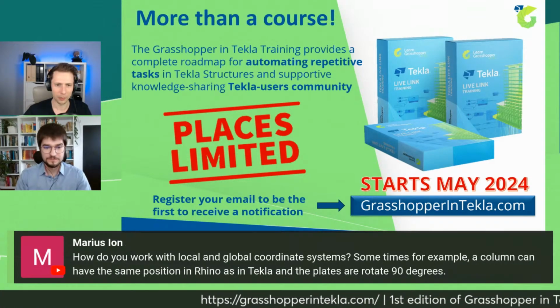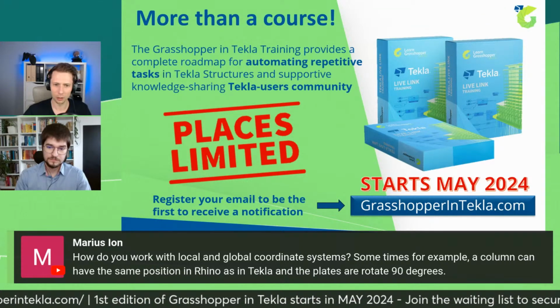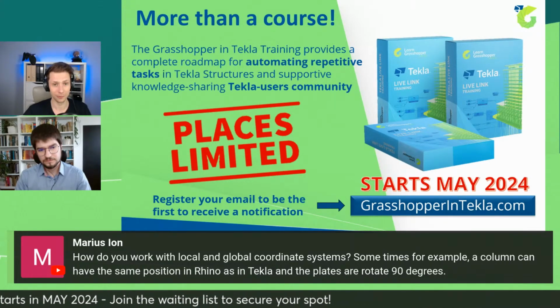A question from Marius. How do you work with local and global coordinate systems? Oh, this is interesting. Sometimes, for example, a column can have the same position in Rhino as in Tekla, and the plates are rotated 90 degrees.